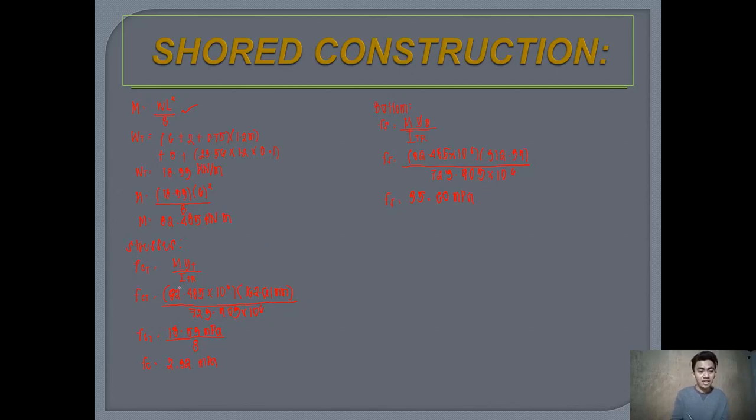Take note, when you are determining the stress at the topmost part of a composite beam, you have to divide the value for My divided by the transformed moment of inertia by the modular ratio for you to be able to determine the stress for concrete. So we have this value. And then at the bottom, you will be able to determine the stress for steel.